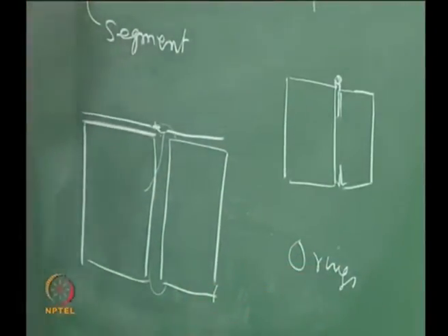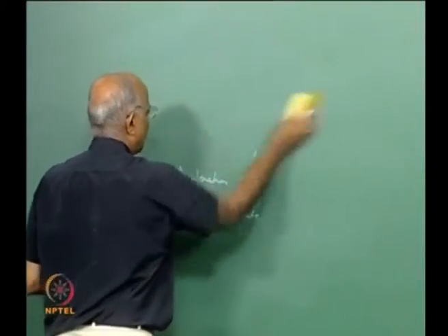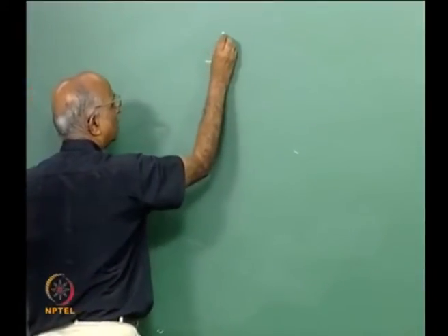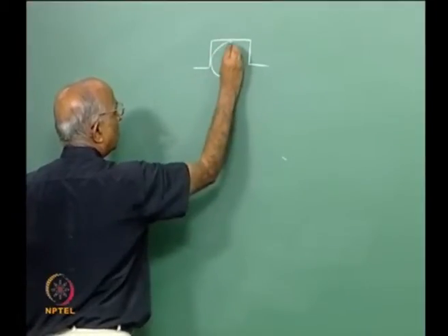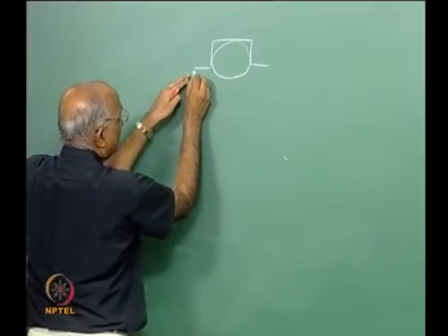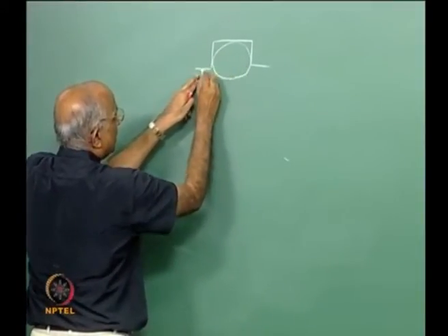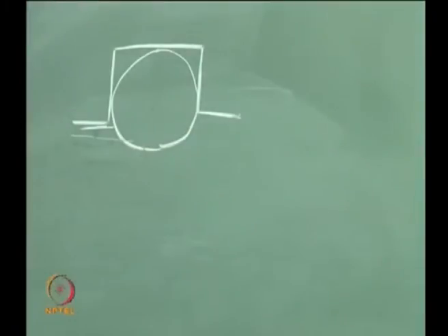Let us try to make a sketch of how the O-rings function. See, how do you assemble an O-ring in any problem? I have an O-ring groove, I put the O-ring over here, and when I assemble this, the O-ring being flexible makes this junction airtight or leak tight, and therefore 2 O-rings are used, and these O-rings are of rubber.